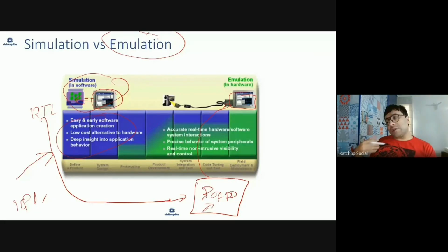So in emulation, the actual processing happens on a particular hardware which implements your design functionality, and you verify it. It runs faster and is able to handle large chips. In terms of verification, they are verifying the same thing. Emulation is just a way of running it on hardware to make it faster and handle big designs.